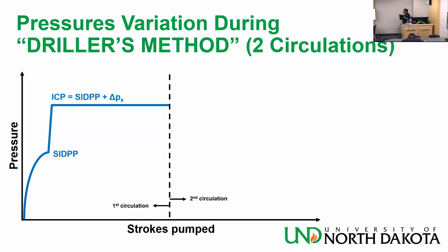And now I have the kick out of the well. Oh, sorry, the kick is touching the top of the well there, the choke, and then it's going down. Okay, kick circulated. The kick has left the well completely, and now I put the new mud, the green mud, inside the well. Okay, I'm pumping green mud inside the drill string.